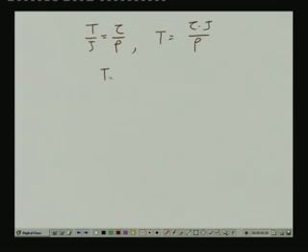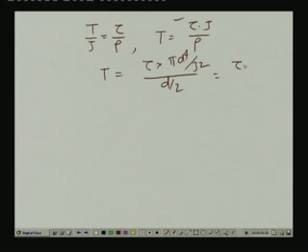So, when we need to satisfy the stress criteria, T equals tau into pi d to the power 4 divided by 32 times d by 2, which is equal to tau times pi d cube by 16. If we substitute the value of tau, which is limited to 32 MPa, that comes as 402.124 Newton meter.